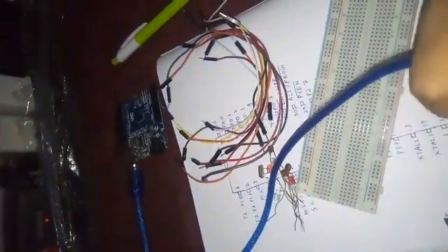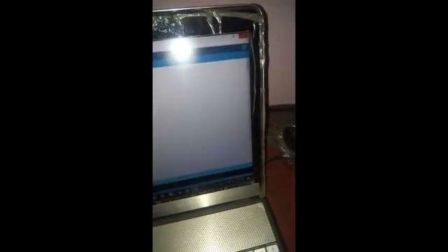Now to get started with, we will be using that Arduino as an ISP, so I will be connecting it here. This is the COM port 9. Go for our main programming, then we'll be closing that, and I am using Keil here to program the 8051. So when we open Keil, then we'll go to project, that one, then create new microvision project.